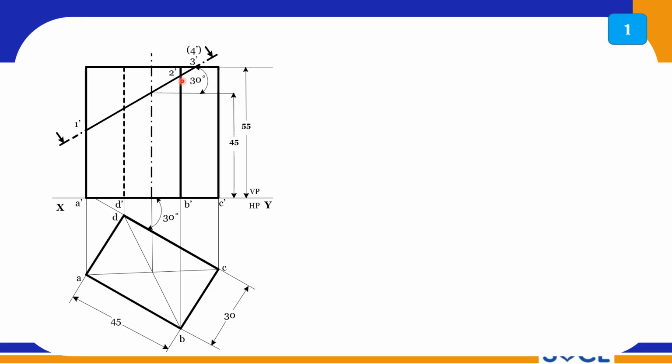So this is 2 dash, and on C, right, it is not cutting C, but it is cutting the top surface, right? So you have two edges here, one is CD and also CB, so it is cutting both CB and CD, so it is 3 and 4, right? So one is CD, another one is CB. So here within bracket I have kept 4.